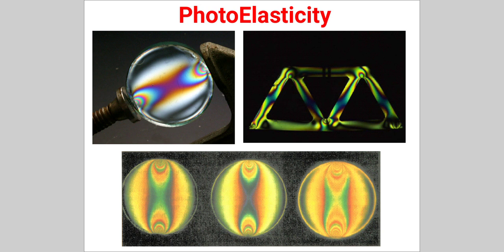Similarly, in the second figure, there are triangular sections. They are subjected to loading, and due to that loading, again their physical properties change, and that change is observed in the form of different types of fringes. In the third figure also, we can observe different fringe patterns. The fringes develop at the top side and the bottom side, because the load is applied from those points.